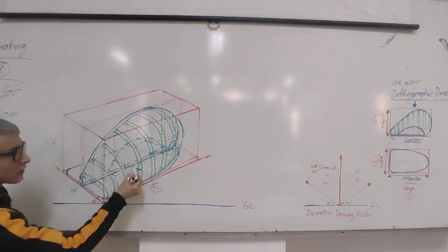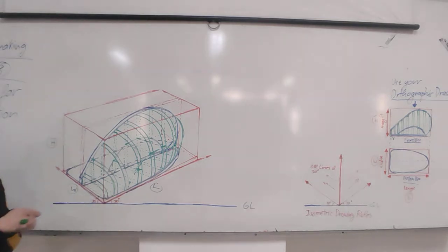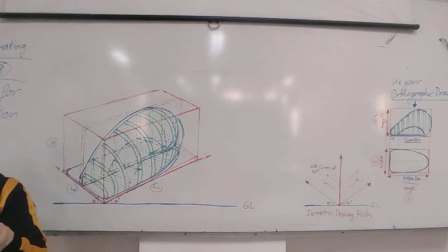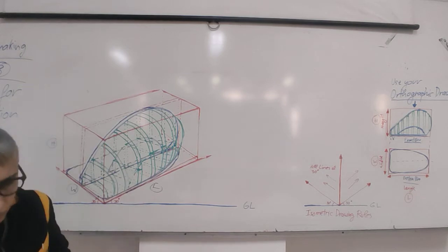So this line here, suddenly something happened to this object. So now, is it a corner? Is it sudden, or is there a radius? Now, in the first step, I will not care about this. I will not care about the radius. I will make it a corner, and if there is a radius, I will add the radiuses later. So from here, there is a sudden change.